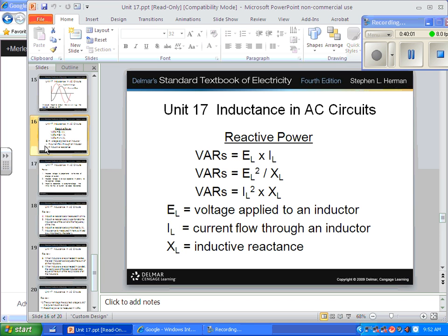What is Edison charging you for? Volt amps. What do they say they're charging you for? Watts. A watt. Watts is true power, the actual work getting done, right? Well, you've got an inductive circuit. It's not perfect, is it? You're not getting everything out you put in. If you're putting in 1,200 VAs and you've got an inductive circuit, which every motor is, right? So if you've got a pool pump in your backyard, are you going to get 1,200 watts of work out of that pump? Heck no. You'd be lucky if you get 70% or 80%, right? Why is that?